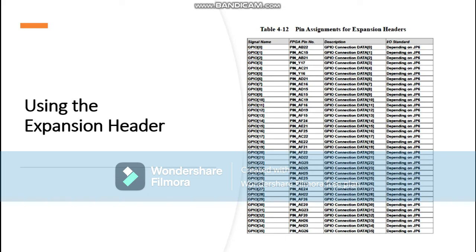The factory default setting on the RS resistor will be 47 ohm, and the RP resistor will not be assembled for single-ended I/O standard application. For LVDS transmitter application, please assemble 120 and 170 ohm resistors on the RS and RP positions respectively. Finally, the table shows all the pin assignments on the GPIO connector.